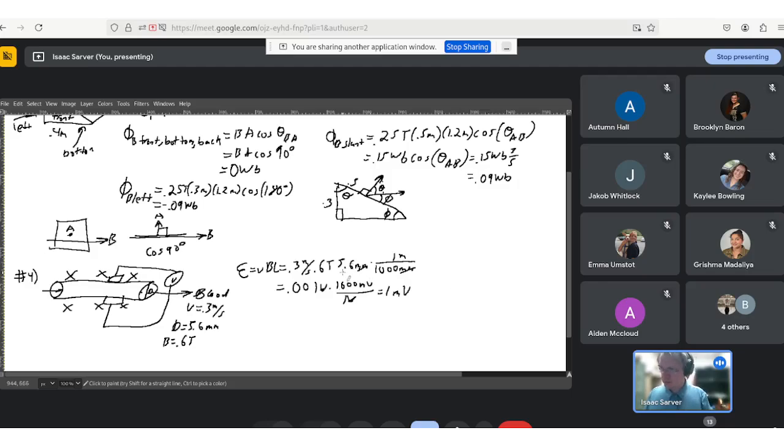So obviously, there you can do your dimensional stuff with this and turn it into a flow rate, and figure out how much blood that is, what volume that is. So that'd be volume per time, so that'd be 0.3 meters per second times the area. That would be pi d squared over 4.